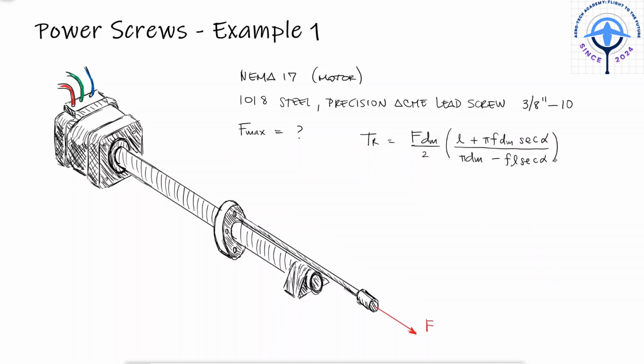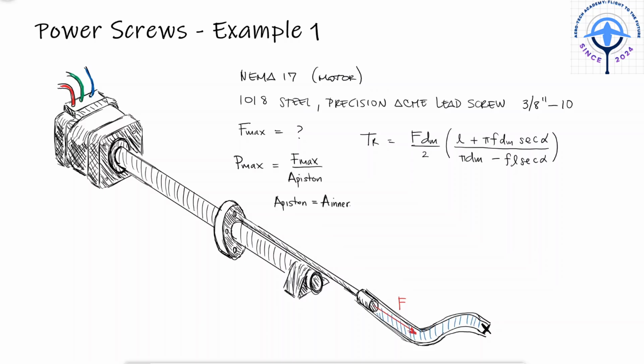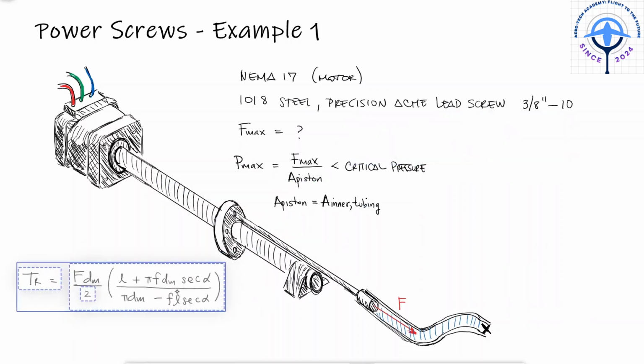The reason we might be interested in that maximum force might be, for example, that the piston is connected to a hydraulic system. So in case something down the line of the hydraulic tubing gets stuck, we would like to make sure that the built-up pressure will not damage our equipment or make the tubing come off of the piston.